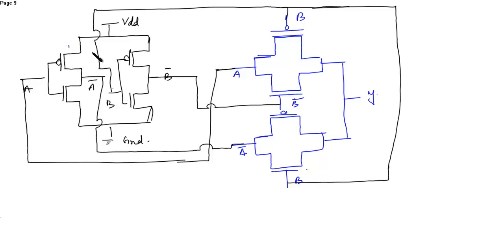As this is, suppose, the PMOS, then you have to take an N-well, then the P diffusion layer inside it in a straight manner like this. But over here you will take the N-well as this and the P diffusion inside it.